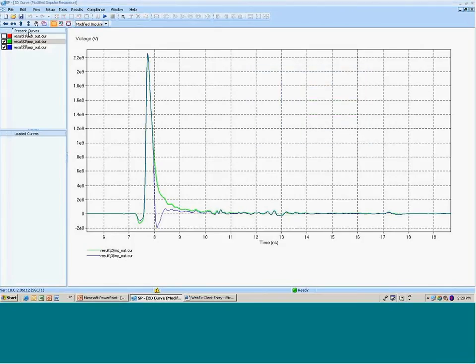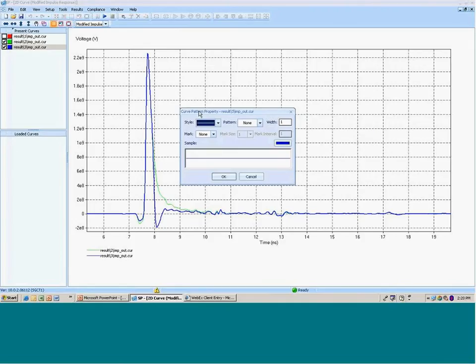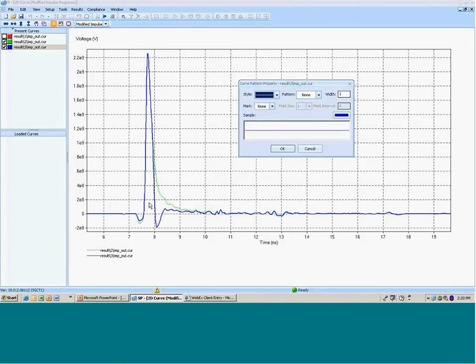And if you contrast that with the result with the 3-tap driver in place, you can see down in this area, this is really the area where the major difference took effect. You can see with the 3-tap driver and the blue response, the modified impulse response is much sharper than this sort of lazy falling edge that you see here with the 2-tap driver. And the difference in that impulse response, the difference in that equalization, is what really cleaned up the waveform in this particular case.